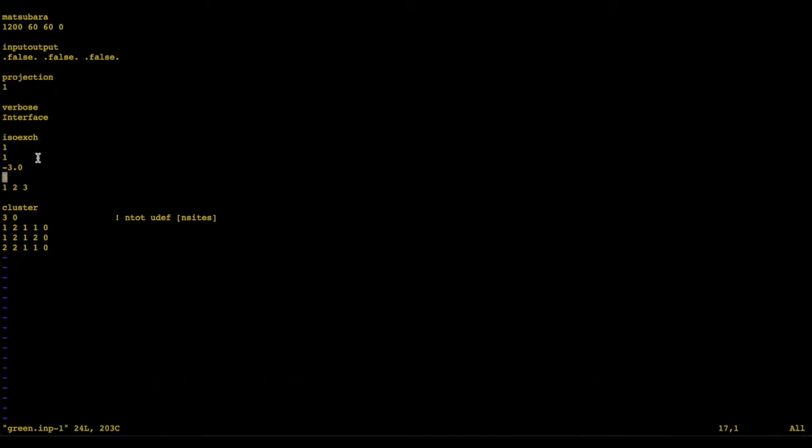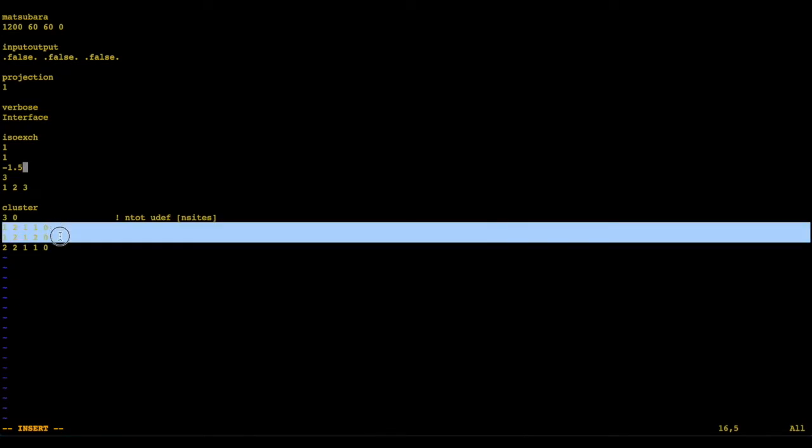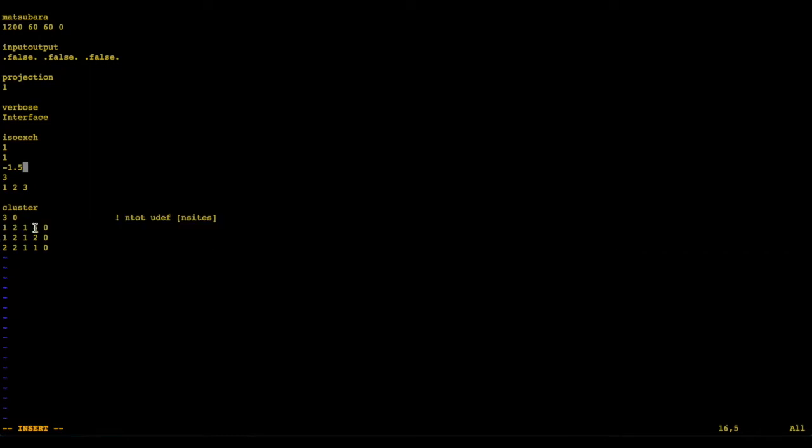This file was generated for the first magnetic atom, which was cobalt, and it has a global index 1. The code will now look for all its neighbors in the radius of 3 lattice constants. To speed up the calculation, let's reduce it to 1.5. And here are the indices of magnetic atoms in the unit cell. And finally, in the cluster block, we specify the states which are used for calculating the exchange interactions. In this case, we only use d orbitals of transition metals. Cobalt-1 and cobalt-2 atoms belong to the same type, but they have two different site indices.